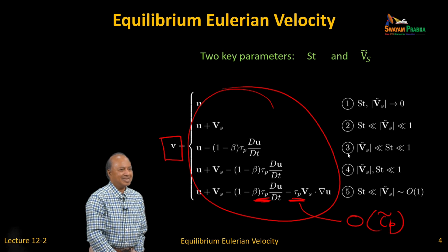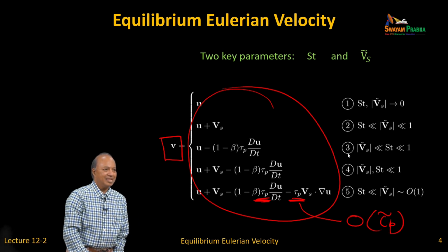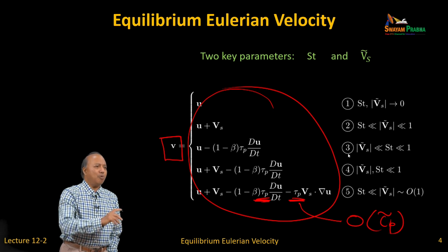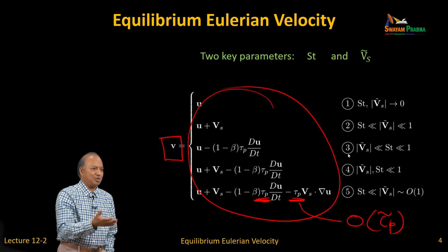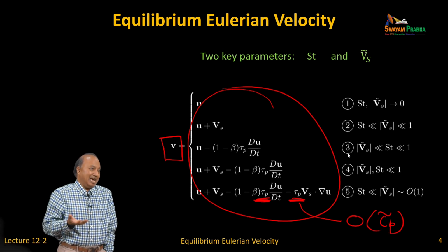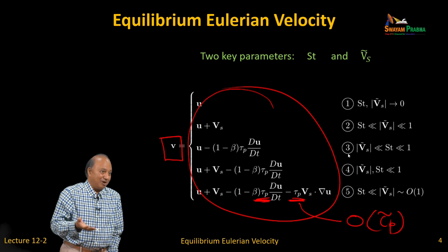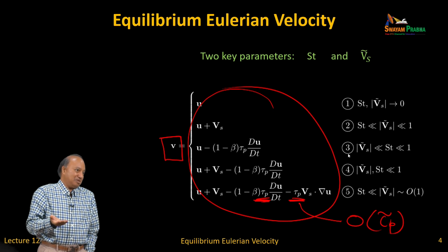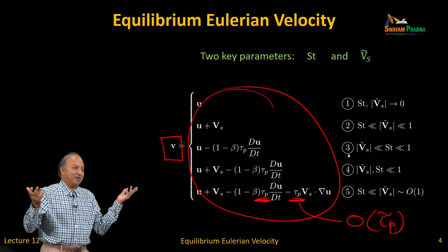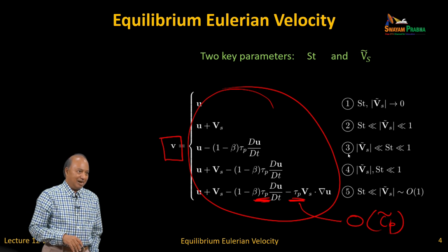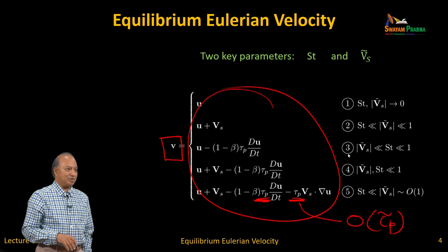Yes. Like, is the Stokes number defined based on settling or based on the shear? You should do both. So in other words, the worst case Stokes number is what is important. If there are many fluid time scales, you want to know, can I neglect the response to every one of them? If every Stokes number is small, then you say, well, the particle is ignoring every fluid variation. It could be due to settling, it could be due to response to a shear, etc.